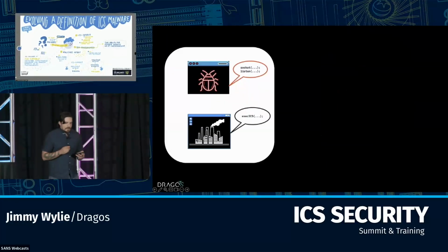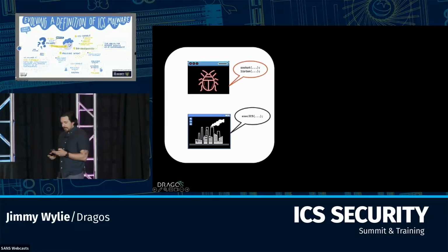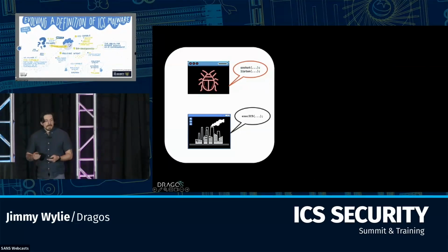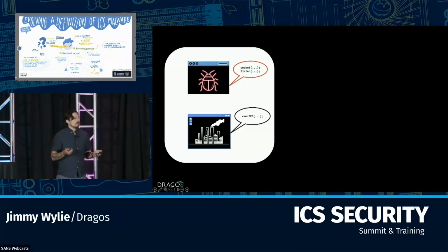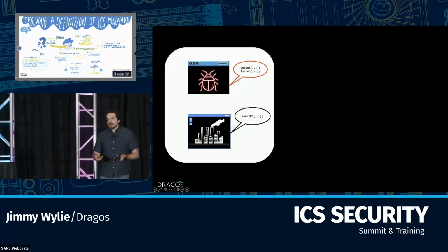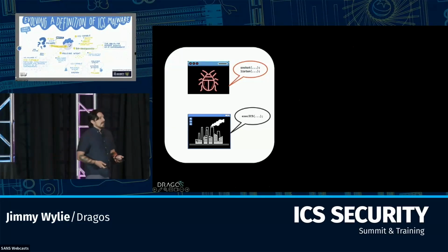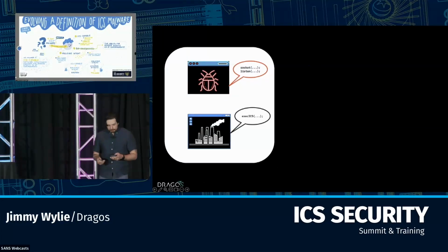Now, the question becomes, is this virus self-contained and independent of its package, right? Put another way, does it only depend on the package as a disguise to gain execution, or is it trying to use some of this ICS capable code? If the container is only a disguise, then no, it's not really ICS capable because it doesn't do anything. And it would act the same way regardless of whatever software it infects. If this thing infects engineering software, it opens up a back door. If this thing infects Microsoft Word, it opens up a back door. It doesn't care what network it's on. It doesn't do any kind of interaction with the ICS environment in any way that makes you think this might be ICS software, much less ICS malware.